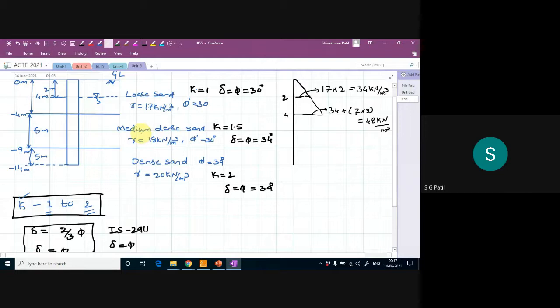Okay, so if you see these culvert pipes they will install, it is just to facilitate the drainage of water in the roads and all. If you would have come across, some bridge will be there. So if this is your road, below this road some concrete pipes will be put, right? So all along perpendicular to your road, just to facilitate the drainage of water.